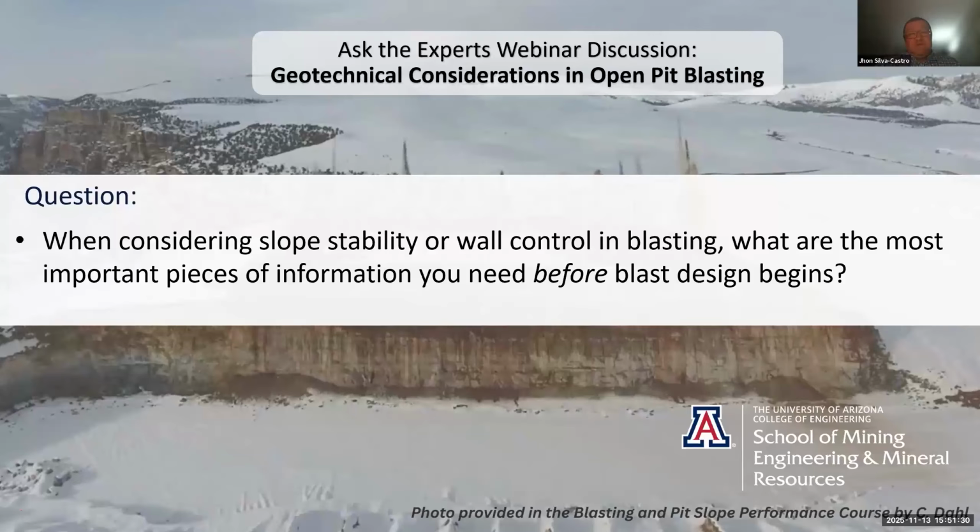I will just summarize all the things that you are saying as limitations and restrictions. You have to control PPV. You don't have that problem. You have to do this blast for fragmentation, as Ray was saying. Also the purpose and the limitations of the blast. Do you have enough free faces? Or is it confined? So all those things need to be accounted for.